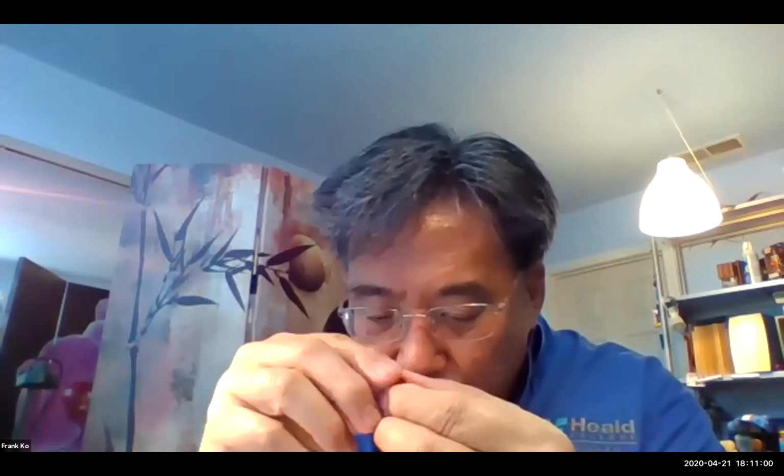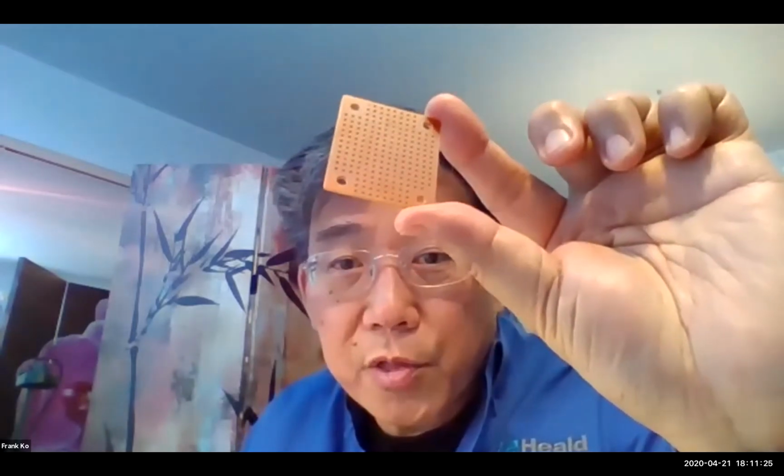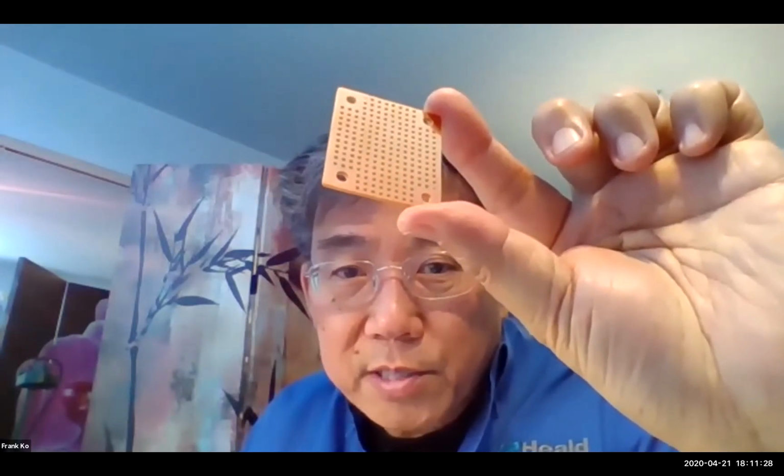We included sockets in the kits for last semester, but the one sample kit that I happen to grab for the squealer circuit for next week is all of these parts, and there is a circuit board. Let me get it out of the bag. This circuit board only has traces on one side. There's no trace pattern and it's not plated through. So your components go on this side, and the wires are soldered on this side.